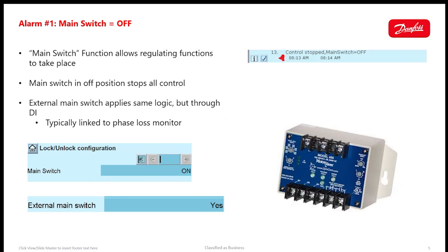And so it's just good to keep in mind that if you're saying yes to that, if you're turning this off, which in general can also be done from the system manager, we are making sure that it's not for an extended period of time unless we know exactly what that change entails, because that will, again, disable the rack and will potentially lead to relief valves releasing CO2 from the system if pressures build up for too long.